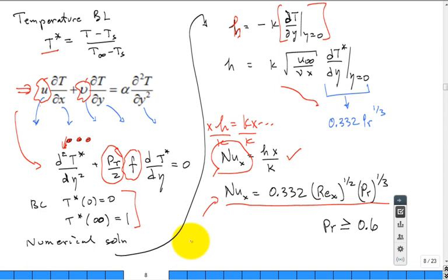This is impressive. But now we say goodbye to analytic solutions to these problems, and we now rely on empirical, what the king dictates. No. What laws Congress passed. No. Empirical means a lot of experimental measurements, and then they look at it and they say, you know, the form of the solution should be something like this. Maybe we should look for the Nusselt number as a constant, Reynolds to a power, Prandtl to another power. And we'll curve fit and find C, M, and N. And that's the game of convection for a lot of historically what it's been.